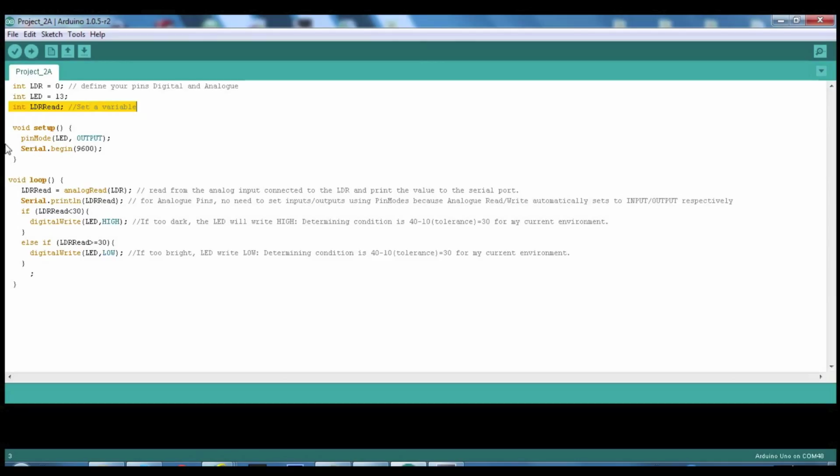2. Pin mode. There is only one pin mode we need to establish, which is the one for the output LED. This helps to set a proper 5 volts for pin 13 so that the LED is able to be bright enough when we call out digital write to output 5 volts at the pin.